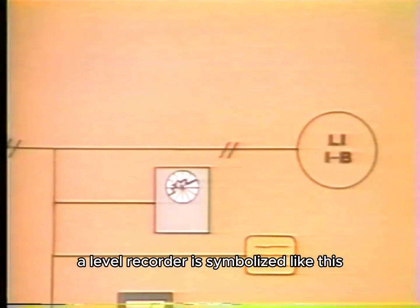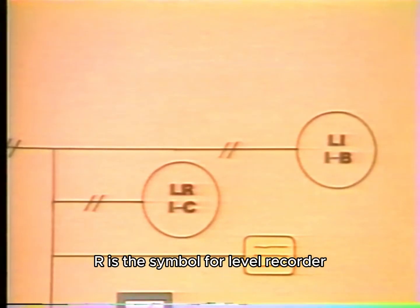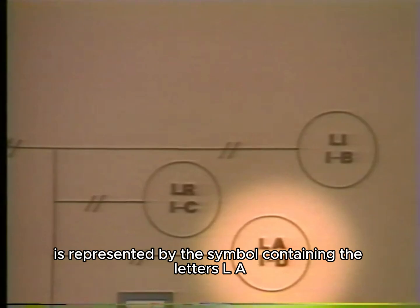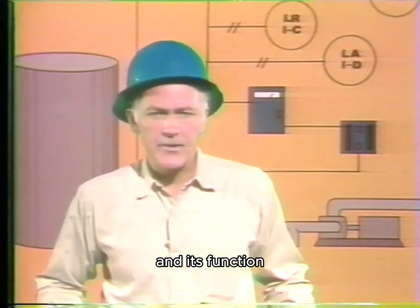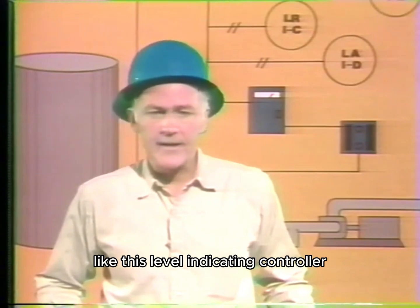A level recorder is symbolized like this, LR. L represents level, and the R represents a recording function. Therefore, LR is the symbol for level recorder. Similarly, this instrument, which is a level alarm, is represented by the symbol containing the letters LA. So far, the instrument symbols have been fairly easy. The two letters in the symbol represented the type of instrument and its function. But what if an instrument has more than one function, like this level indicating controller?